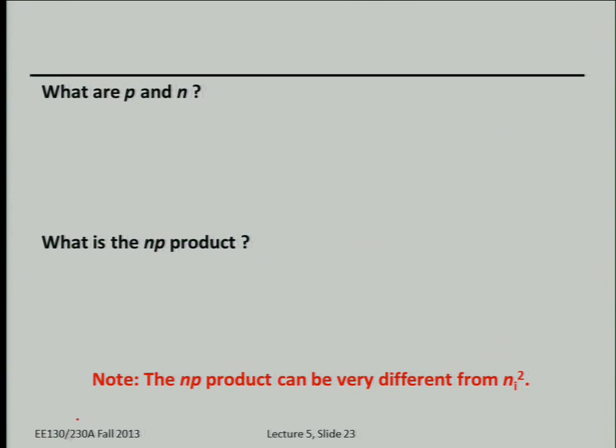So right now, let's calculate the net concentration of electrons and holes. In a p-type semiconductor, like in this case, the total hole concentration is the excess hole concentration plus the equilibrium hole concentration. For electrons, the same thing, right? Delta N plus N0: excess electron concentration plus equilibrium electron concentration. We just got those values, you just remember, 10 to the 14th, okay?